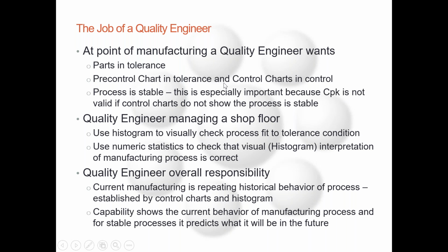Could be over a week, a month, but it's looking at whether it is following a consistent set of behavior. And it also determines that we have a stable process so we can trust things like CPK. When you're using one number to interpret the data, you need to know that it's based on good information, and that's what stability gets you.